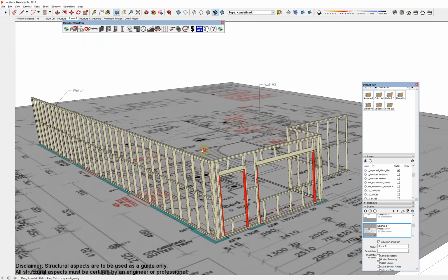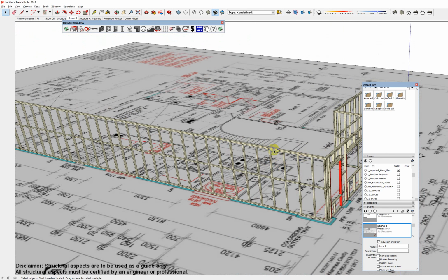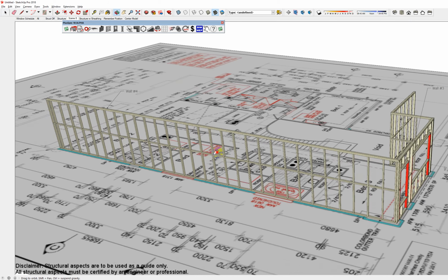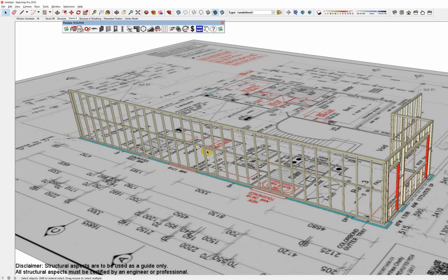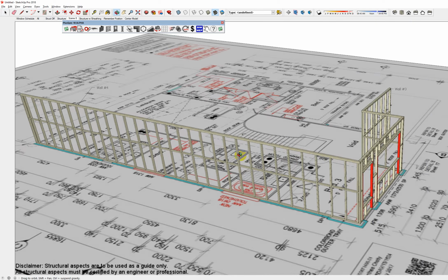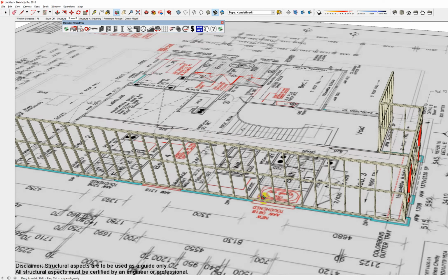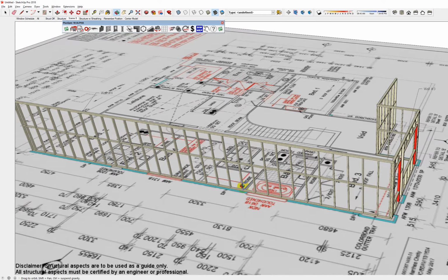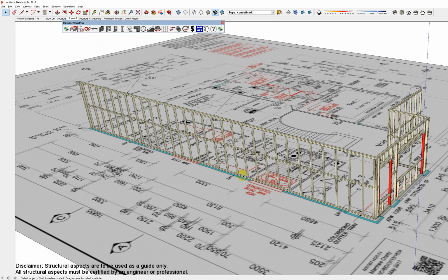doing a takeoff. Now, before I mentioned as well that we drew this wall long and we can't buy lumber in this size. There's a couple of ways, and guys, we do deliver specific tutorials or one-on-one training according to the user and what they want to do, because there's a lot to Plusspec. However, it's easy to use if you just break it down into your sector of the industry. And breaking walls down into sizes and associating blocking for walls or junctions and other framing items is what I'm going to get into next.